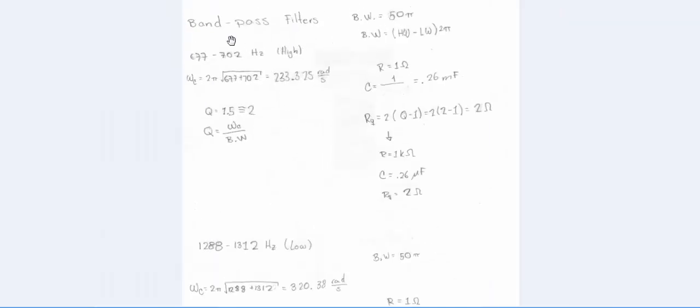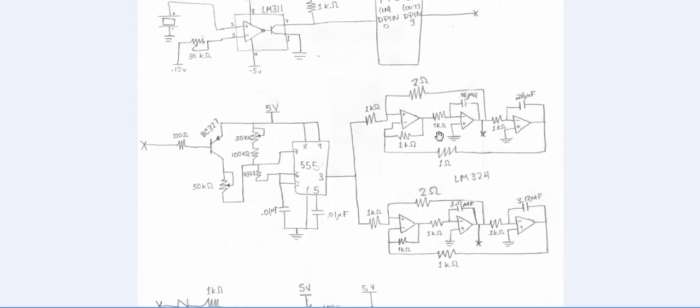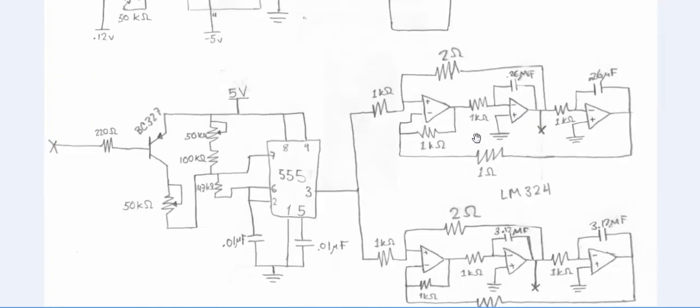And finally we got the bandpass filter that it's this one. As I said before, it's a biquadratic filter, so the values of all the resistance, and not including this, this is important, the value of these 5 resistance, my bad, is going to be the same, and the value of this capacitance also is going to be the same.